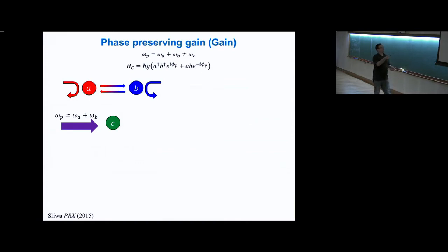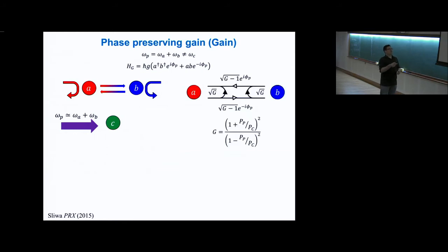But once again, if we look at what happens to light coupled into and out of these ports, any light incident on A is reflected with some gain root G, B the same. Again, now there's this conversion, but this time with gain, but with this same conjugate phase shift if you go one way or the other. So these devices are not non-reciprocal, because I can't formally build an interference circuit out of them, but they have the seeds of non-reciprocity in them.